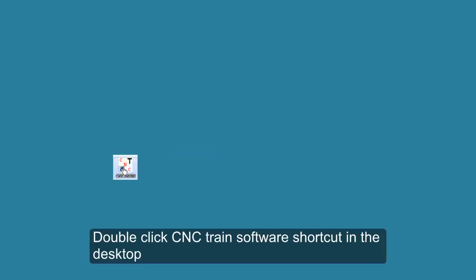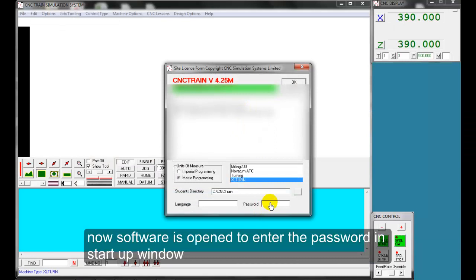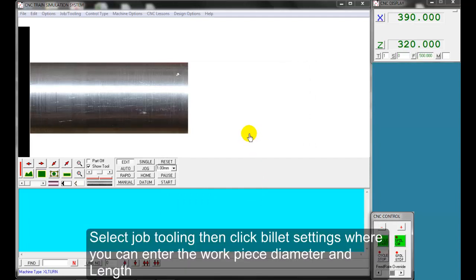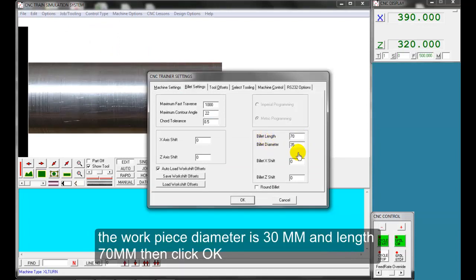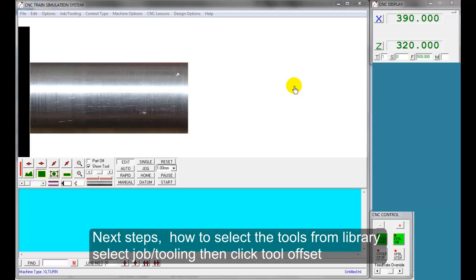Double-click CNC Train software shortcut in the desktop. Now software is opened. Enter the password in startup window. Then click OK. Select Job, Tooling. Then click Billet Settings. Here you can enter the workpiece diameter and length. Enter workpiece diameter is 30 mm and length is 70 mm. Then click OK. Next step, how to select the tools from library.